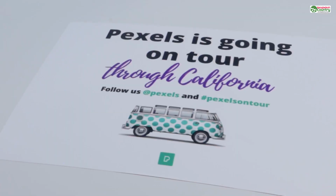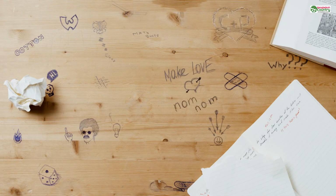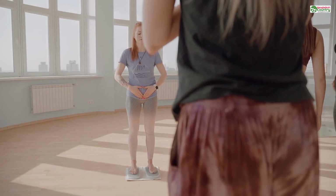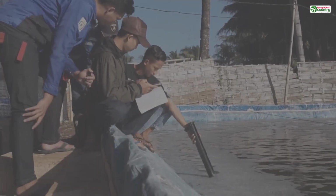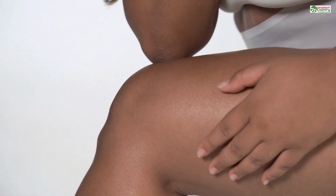Now the next big question is, how thick should the walls be? This is the Goldilocks decision. Too thin and your model becomes incredibly fragile, like a real eggshell. It might break during shipping, or even during post-processing at the facility. Too thick and you start to lose the cost and weight savings you were trying to achieve in the first place. You're back to printing a solid chocolate bunny.